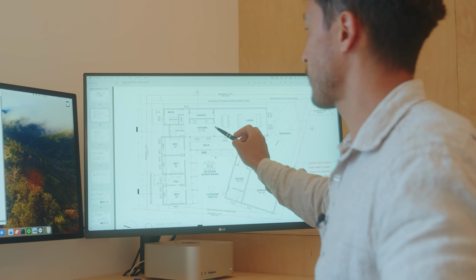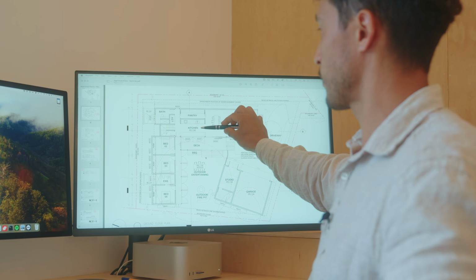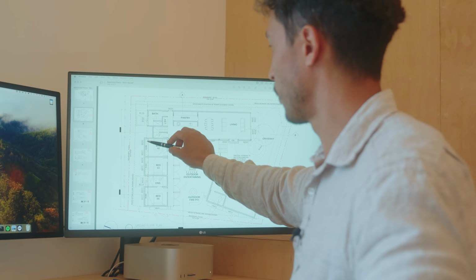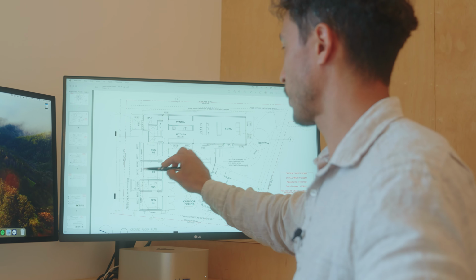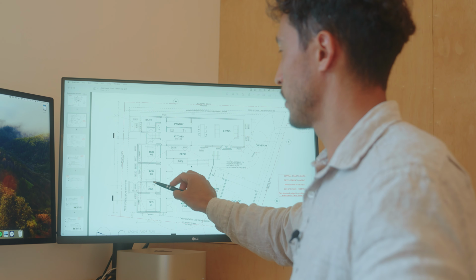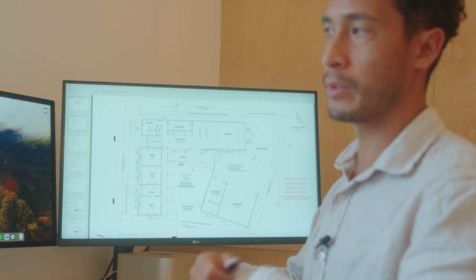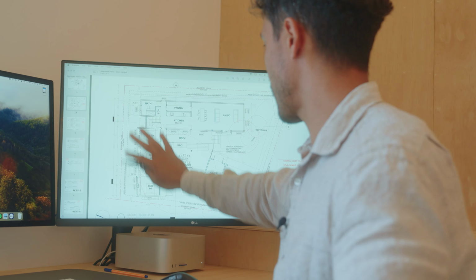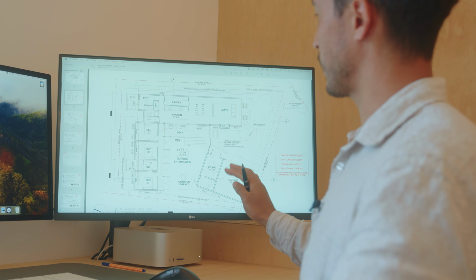And then at this stage, we'll just make assumptions. So we'll allow for provisional sums for the kitchen, say 40 grand for the kitchen, wardrobes 5 grand, and we'll go through and quantify all that. And we'll make assumptions about the ensuite, the bathroom, whether it's tiling, whether it's render, all sorts of things. This is about capturing as much information as we can, making assumptions and then presenting the client with a preliminary estimate based on what I would call almost a concept design. And that's when we start figuring out whether we wind up or scale up on the next developed design, or we scale down in terms of trying to get it to an achievable budget.